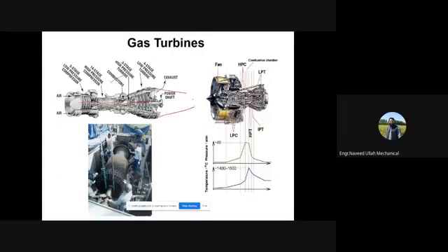Okay, this is the kind of nozzle we have, right? And this nozzle is basically used to accelerate this exhaust, and the velocity that is leaving this nozzle will be obviously very high, and that jet velocity as a reaction is basically producing a thrust in the forward direction. So thrust production happens in the forward direction.